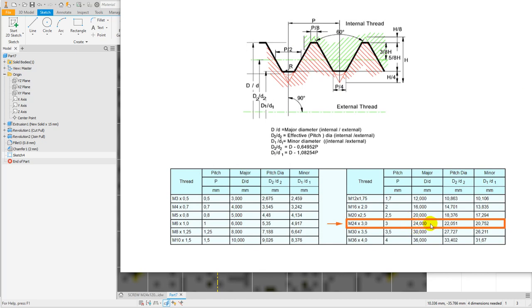You see, when we made the conventional thread, we didn't know what is the pitch. The pitch for M24, the normal pitch, is 3 millimeters. This was chosen as default. M24 without any specification or suffix after is normal, and the normal is 3 millimeters. What we have here, the pitch, this 3 millimeters, the major diameter, the minor diameter, the red is the thread, the green is the nut. We now are concentrated on the red, and the profile for the red is a small arc here and the right side.